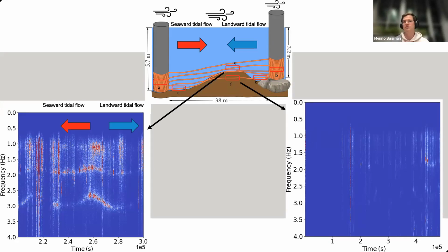We can still see some small features, but it is muted a lot. This is also intuitive because the movement happens mainly in water, of course, and hence if we bury our fiber, we will not really be able to detect this movement. And that can also be an interesting method to measure, for instance, cable burial or see if your cable is exposed in water.